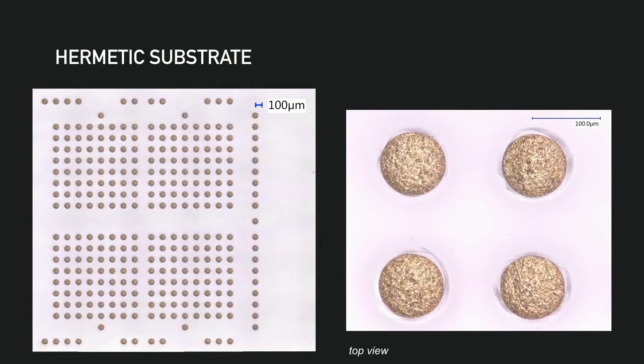Standard processing also requires exposure to high temperatures, typically over 700 degrees Celsius. At these high temperatures, the coefficient of thermal expansion, or CTE mismatch, between the insulator and the conductor can cause circumferential cracking or interfacial gaps during the cooling phase.